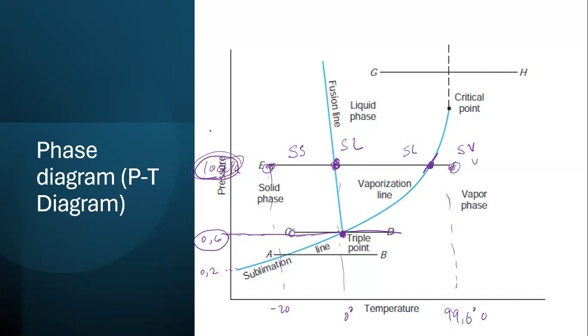Okay. And then as we go up to very high pressures, remember 20 megapascals, not 40, that's supercritical, but for water, 22, I think 22 point something. Remember, we did that in the previous sessions. So around 20 to 22 megapascal, we can have what you call the critical point. Remember, what did we say? What is the critical point? It's where we cannot distinguish the phases.